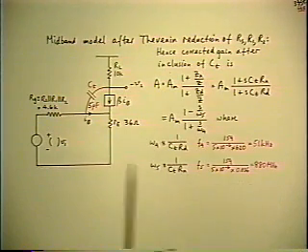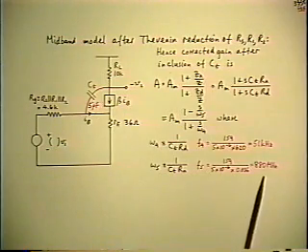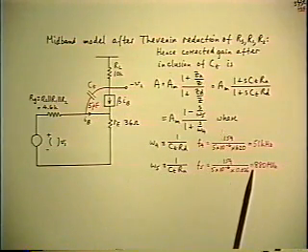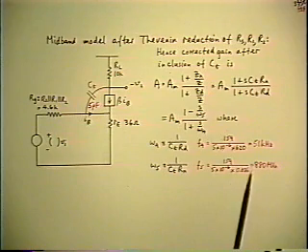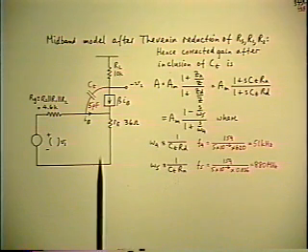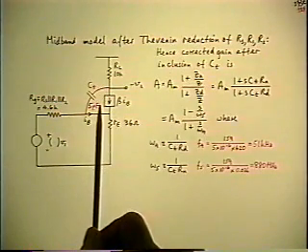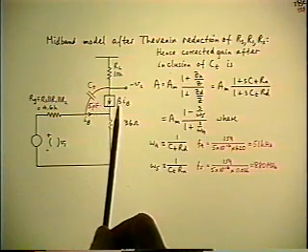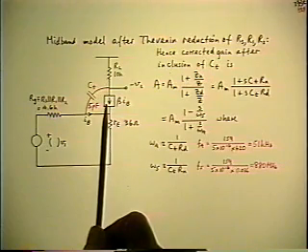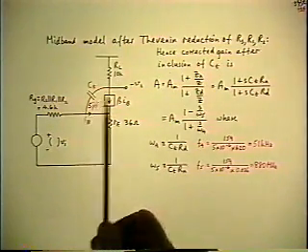So, because of the numbers, you may not have noticed the fact that the right half plane zero exists. But it's not too hard to visualize some circumstances where the numbers may be radically different. For example, suppose the CT were not 5 picofarads, but 5 nanofarads. Not because the transistor would be that lousy, but you often purposely put a capacitor in that position, externally.